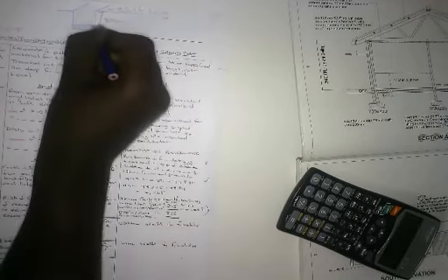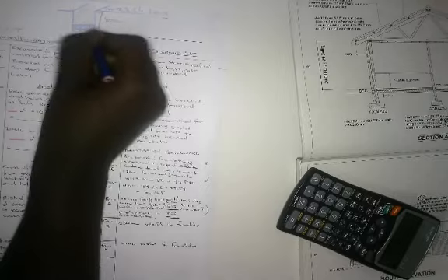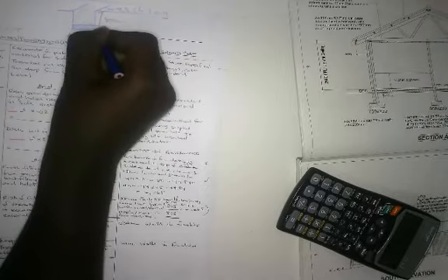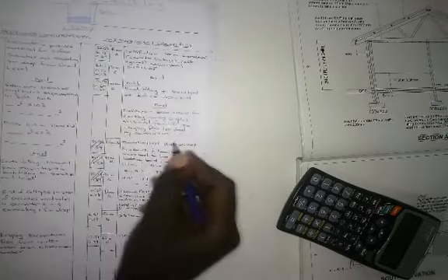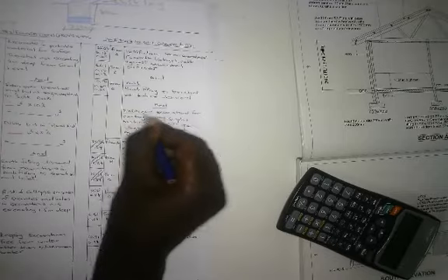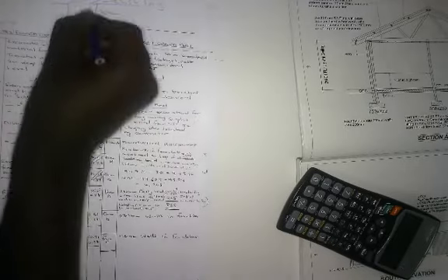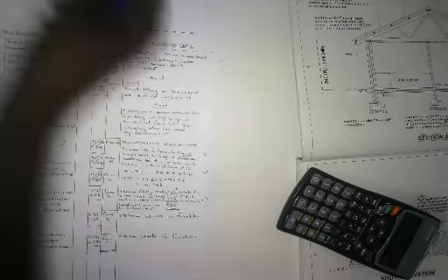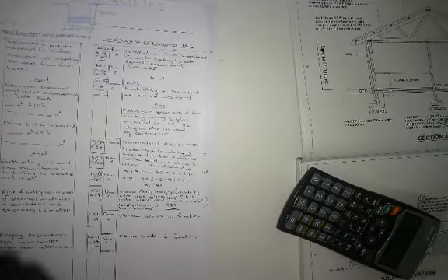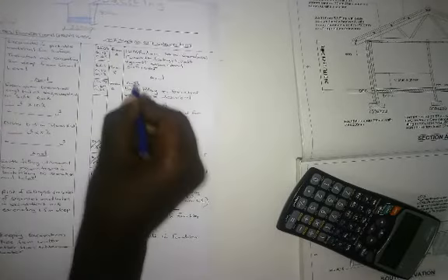But now, since we're going to cast a concrete footing here, while we are calculating the footing, we are also saying now let's deduct that soil we put back. That soil must go to cut away.